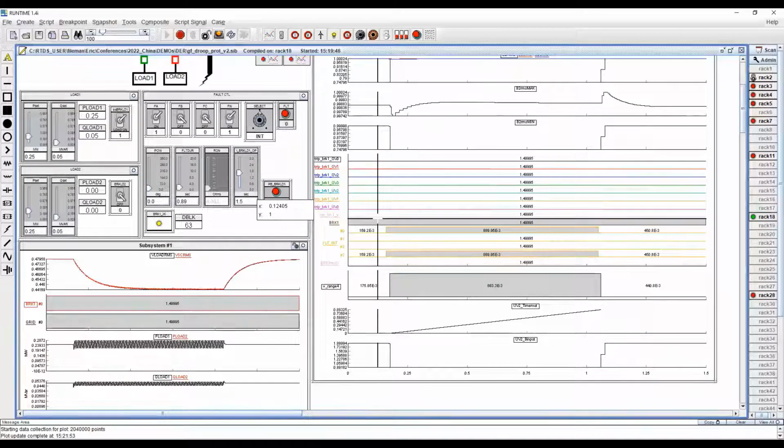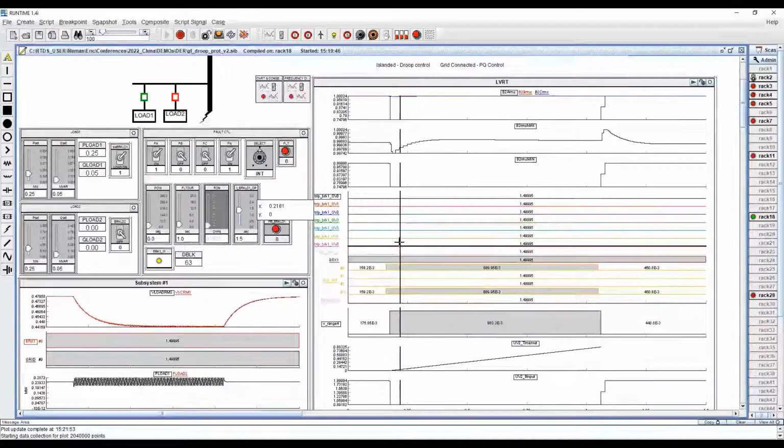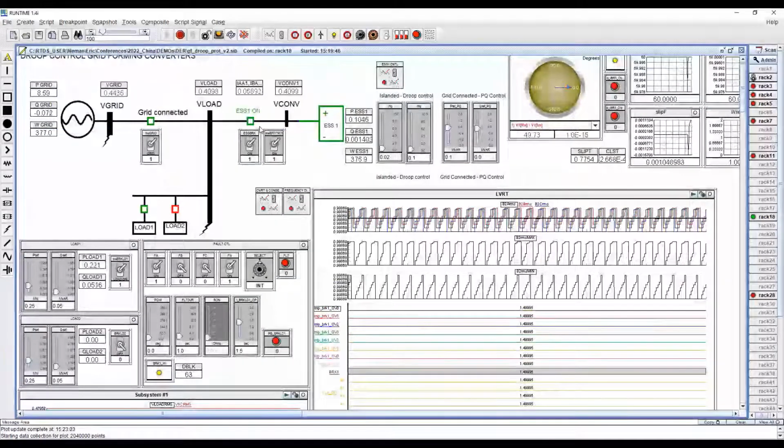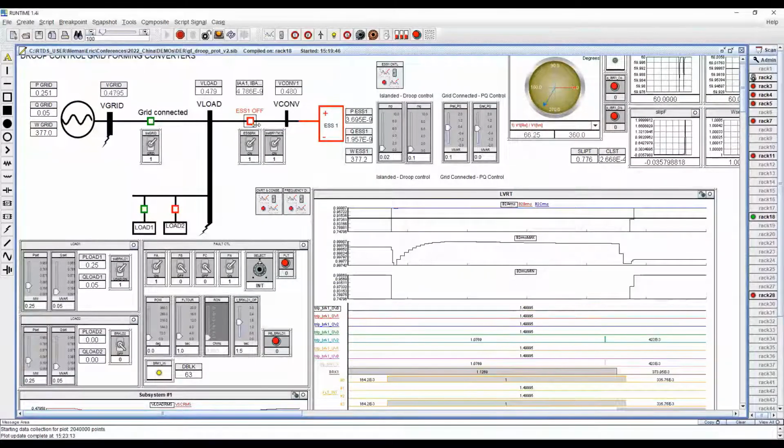Next, let's change the fault duration to 1.0 second and redo the test. Let's do update plot first. And then we can reapply this A-to-ground fault with a fault duration of 1.0 second. Now this time the breaker was opened.